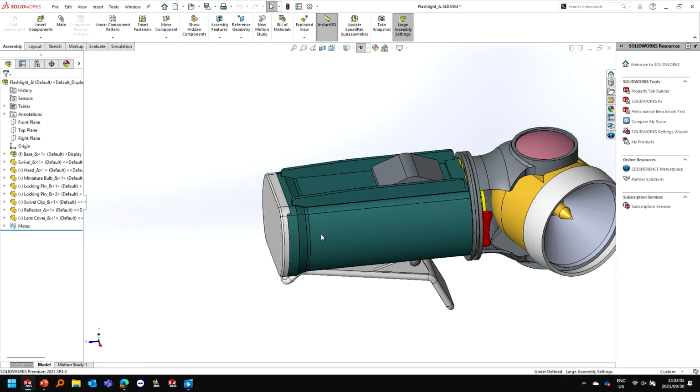So if you know there's a part that's hampering you from opening an assembly, go and open that part, simplify it, create a configuration, don't call it Rocco. You can if you like the guy. He's actually a very nice guy. But call it simplified, and then when you open it, use advanced. If you get stuck, ask us how.